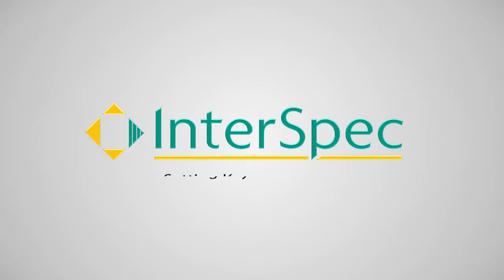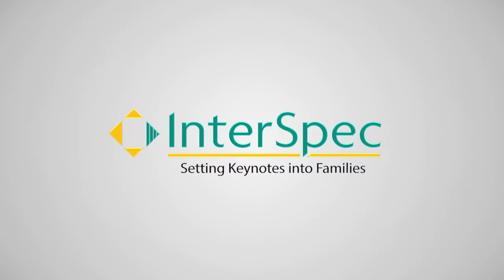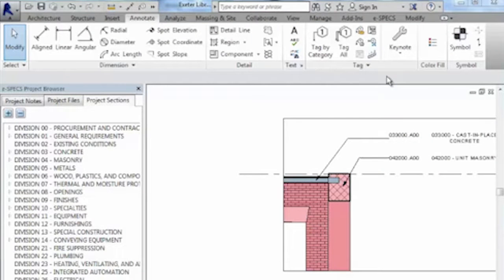In this session, we will use the keynotes we created in the last session to populate the keynote parameters in our Revit families. Although you can set family keynote parameters directly from Revit, it is much more efficient to set them through the eSpecs keynoting dialog, since you can set keynote parameters in multiple families at the same time.